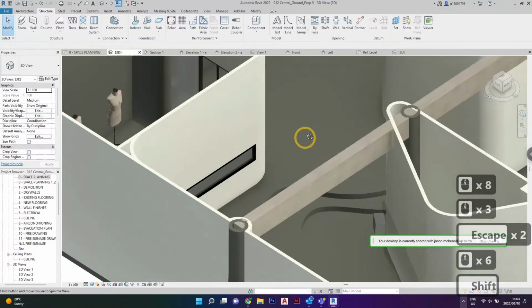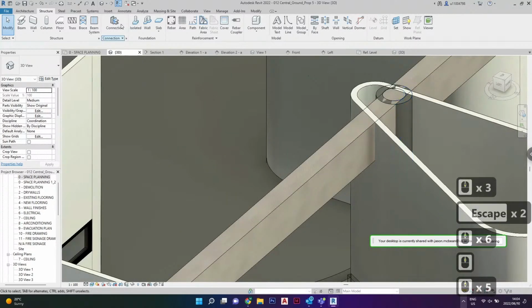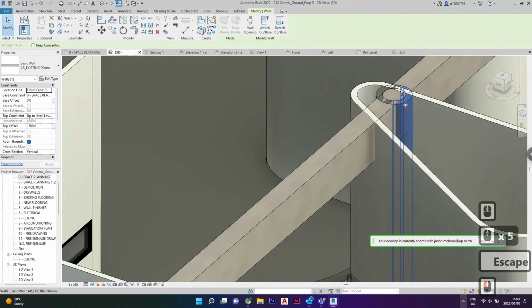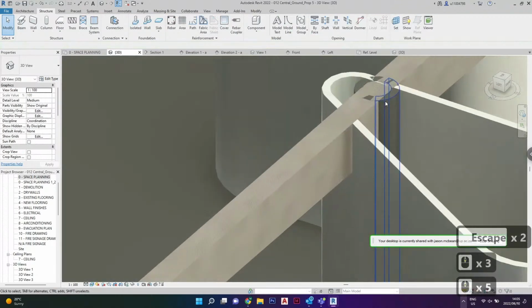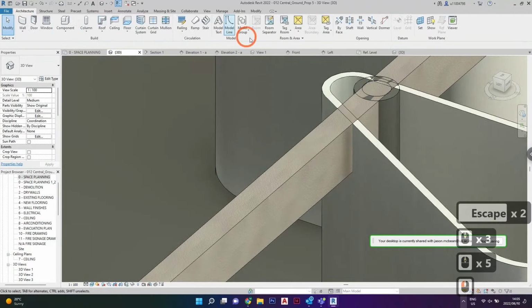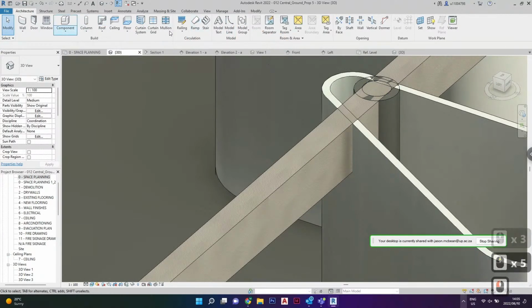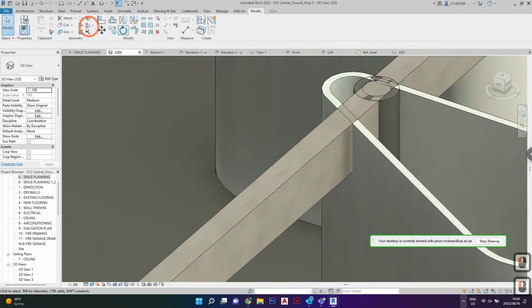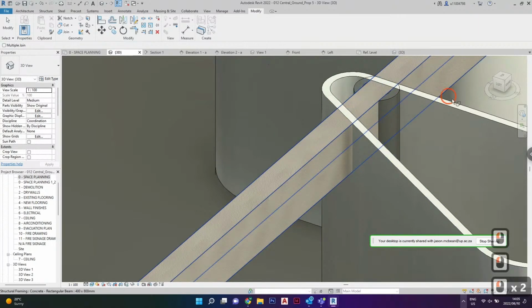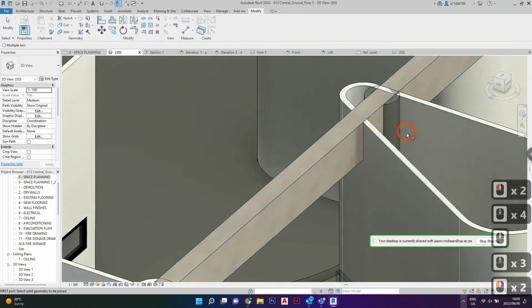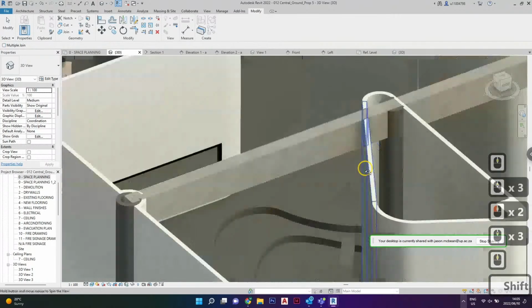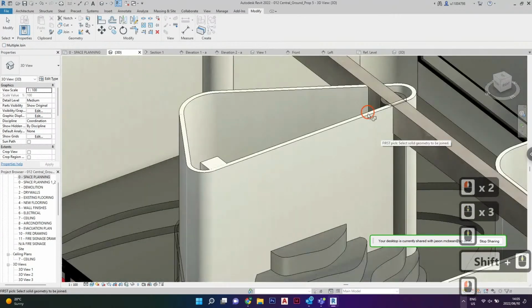For what you're doing, watch this. I'm going to show you this. What is this made out of? What are these extrusions? I just did a drywall layer. Okay. But technically, watch this. You can join the stuff. If you go to Architecture and you go to Join. Yeah, that's what I was wondering, if I could just go modify, join. Watch. Oh, perfect. That's what I want. Check that out. That's cool, hey?